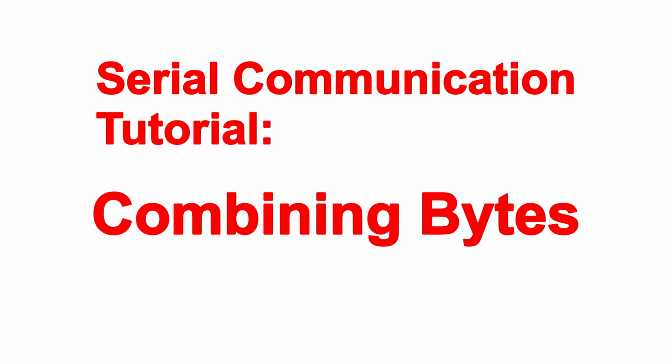When working with sensors or any external devices, oftentimes you'll need to receive numbers that are pretty large, into the thousands or even millions. If you're accessing this data through an I2C or serial interface, you can only receive 1 byte at a time, and the maximum value of a byte is 255. In this video, I'm going to show you how to combine or concatenate multiple bytes into one large value.